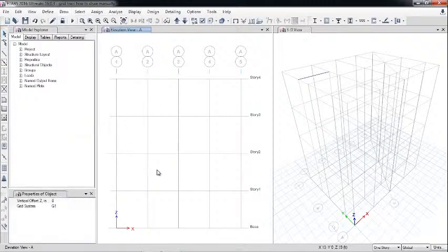Here is offset. So for example, that will be 6 feet above or 7 feet above. I am putting 84 inch, okay, 7 feet from above this point. So here is the reference plane 1. You can also rename it. So I have drawn the reference points and reference plane, and you can see all these things in the edit stories and grid systems.